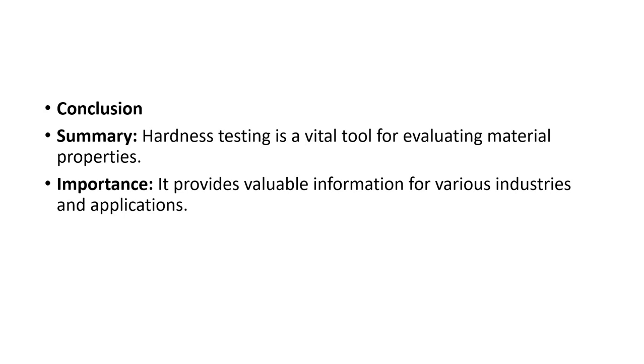Conclusion: the summary of hardness testing is that hardness testing is a vital tool for evaluating material properties. Hardness testing is important to calculate various material properties. Brinell depends on the diameter of indentation, Rockwell depends on the depth of indentation, and Vickers depends on the diagonal length of the indentation. Importance: it provides valuable information for various industries and applications. Use various hardness values of material for design engineers, research engineers, and any other fields.